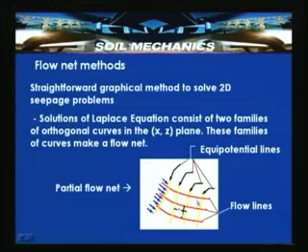Generally, flow nets need to be constructed such that it should be possible for us to insert a circle having certain dimensions, not necessarily identical circular dimensions, where the flow is occurring in this direction. The space between any two flow lines is called a flow channel, and in the partial flow net which is shown here, two flow channels have been shown.